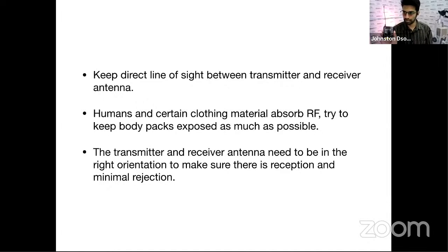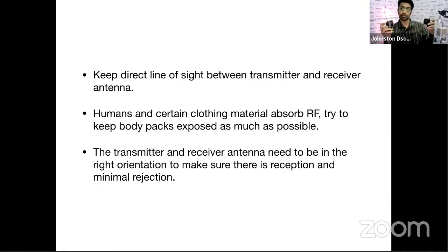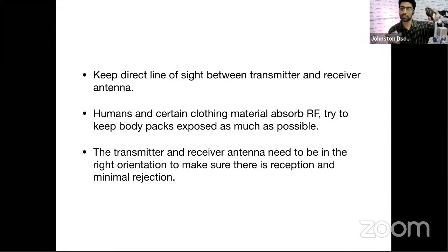Okay, so if your transmitter is set up this way, you make sure that your receiver also is set up this way. Don't put a receiver this way, or don't put the transmitter this way, or don't keep it this way also. It's not going to pick up anything. So they need to be parallel. Okay, a little bit of angle is still okay, but depending upon the distance, sometimes if you're lucky, things might just work depending upon the surroundings. But don't take that risk. If at all you're putting your transmitter straight, make sure your receiver is straight. If your receiver is put in any other direction, make sure that the transmitter is somewhat parallel to it.